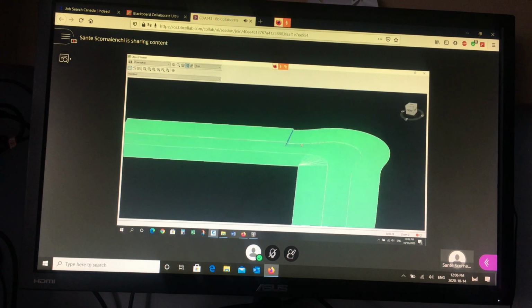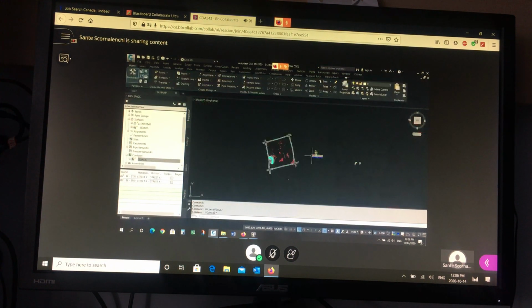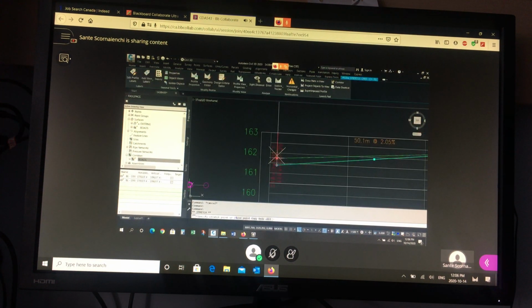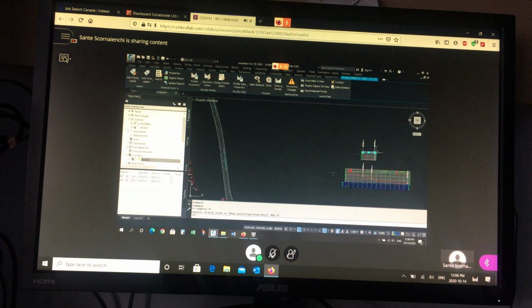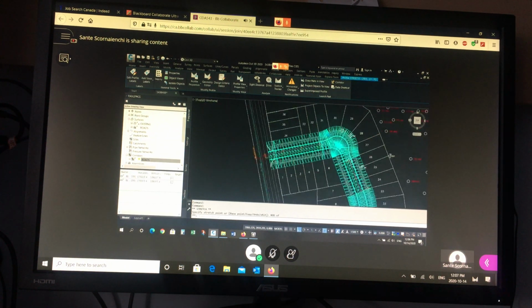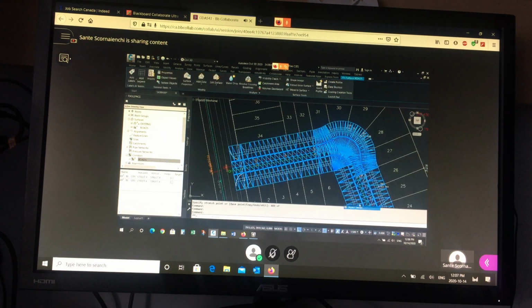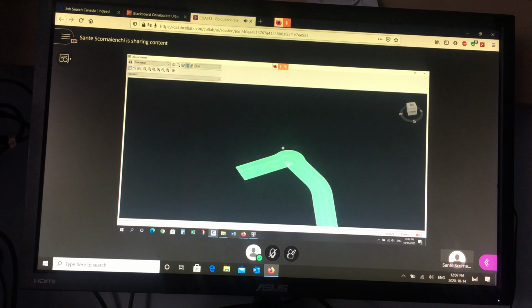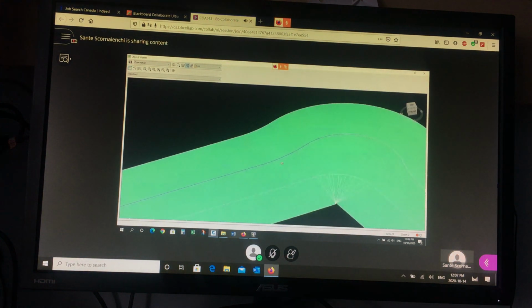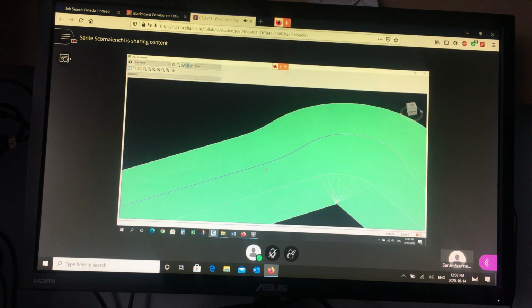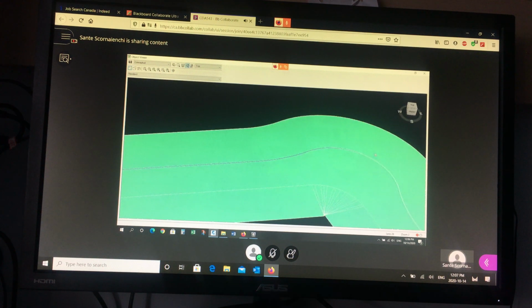It looks like my profile of my gutter is too low. It doesn't match this part of the road. So if you check your projections and stuff, you say, oh yeah, I forgot to snap here. This should be exactly here. And then if I rebuild the surface and look at this in 3D again, yeah, that outside edge looks pretty good now. Everything looks nice and smooth. I don't see a step there anymore, so the outside gets modeled properly.